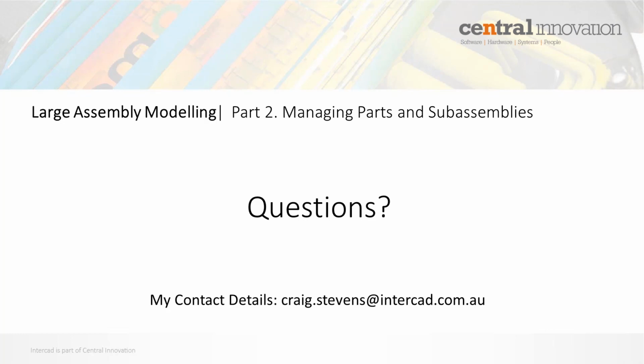When you get into the part, the simplified configuration will be there, but you'll just need to set up what you want to suppress or change in those particular simplified configurations at the part level. You can't actually really determine that at the assembly level. It just sets up that configuration in the model from that part.